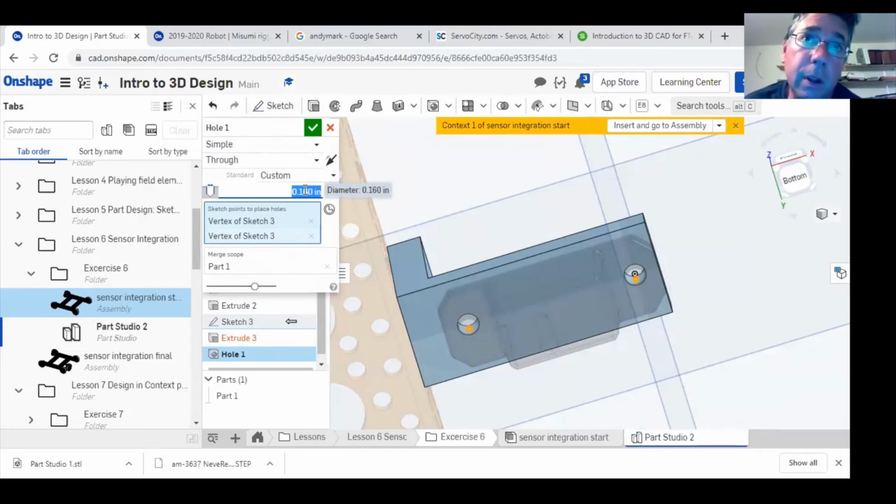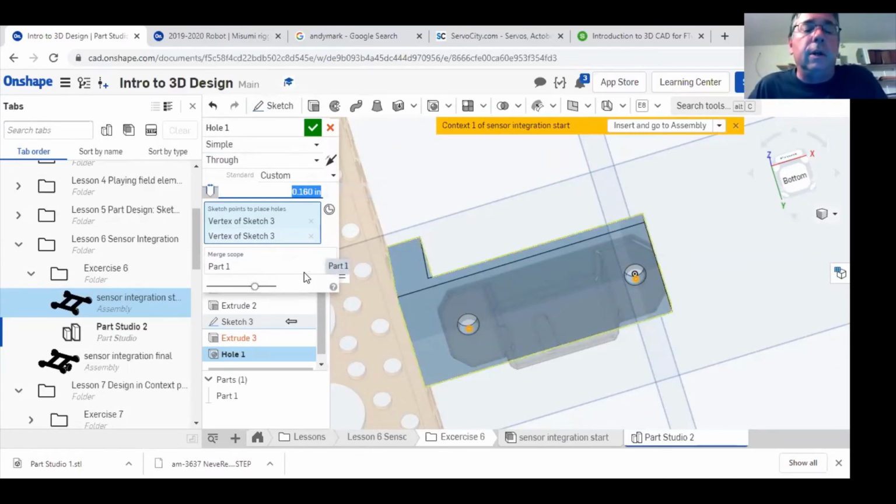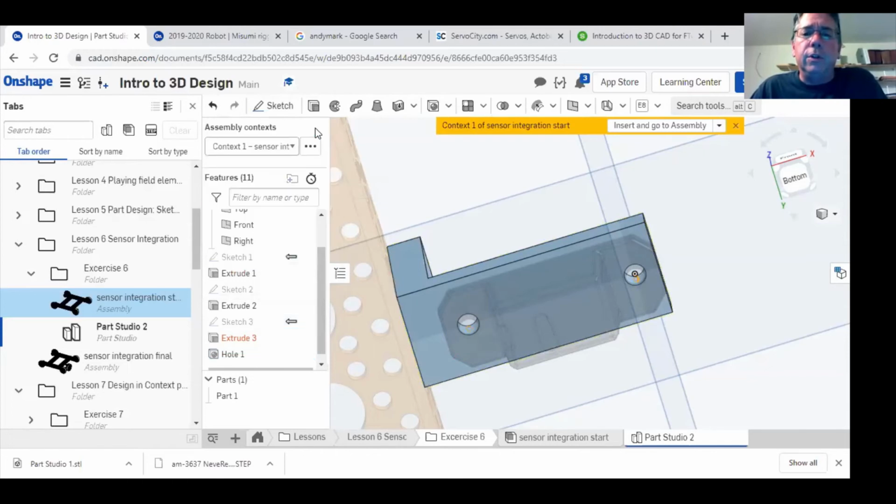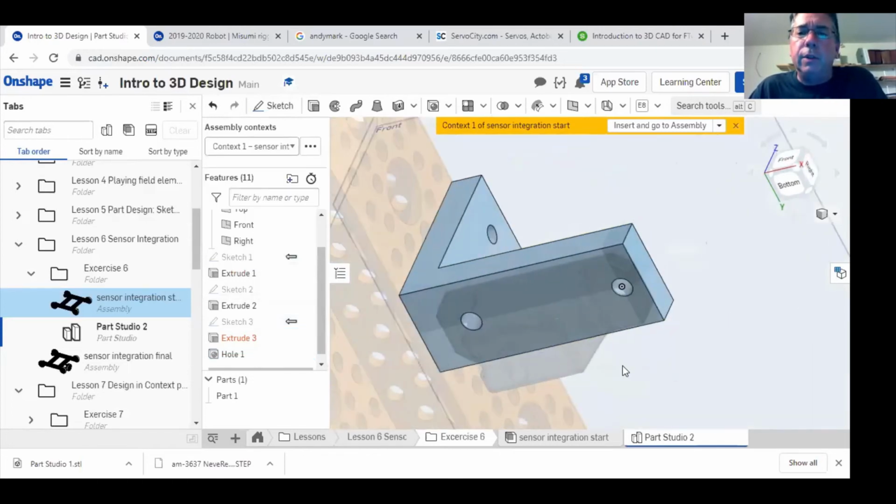The reason I use 0.16 is if you use a hole smaller than that on our 3D printer, the screws interfere. That's due to the innate inaccuracy of extruding out the filament and trying to 3D print holes. So it's better to print the holes a little bit bigger so the screws slide through. Most everybody's using PLA material. You really don't want to have to come back in with another operation where you take a hand drill and try to drill the hole out or fight the fact that the screws don't go into the hole. So tolerances are a whole other discussion in life on design that we won't have today.